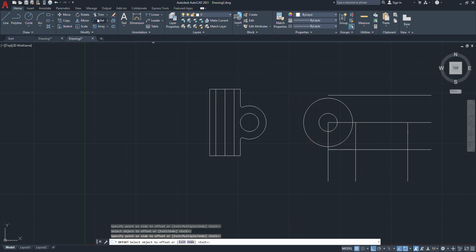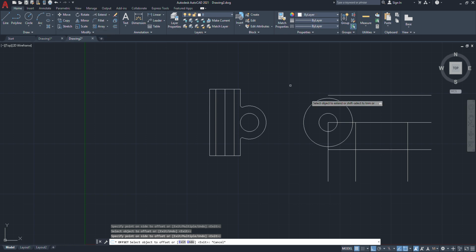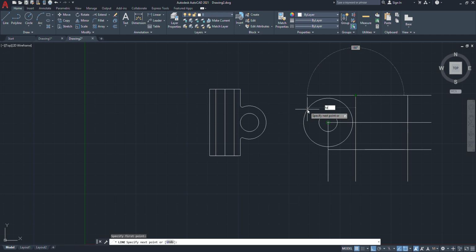Now let us just extend this line to meet that line here also. Okay, now we will do one thing, enter. Now we just draw a line from this junction tangent to this circle. So for that just type tan, to this, show the circle.